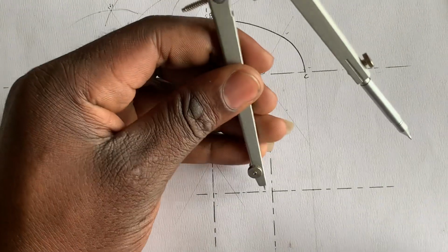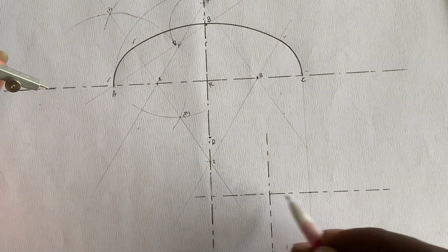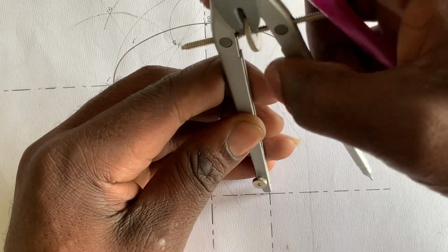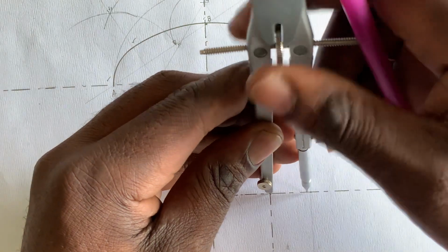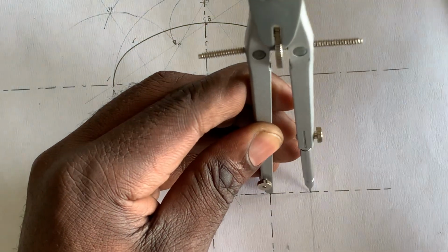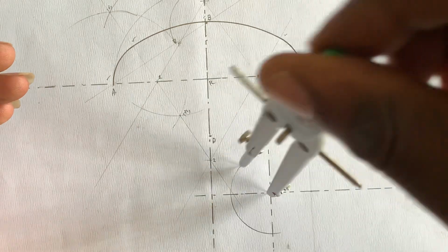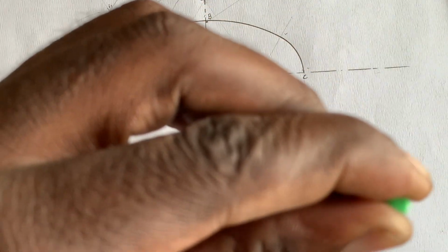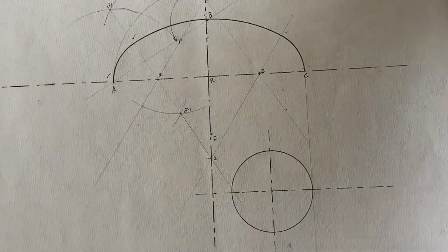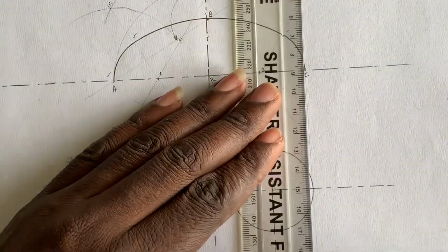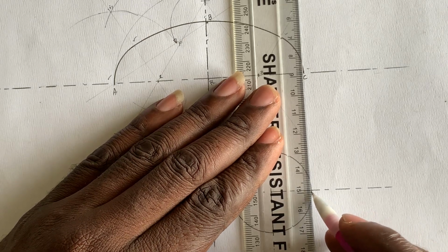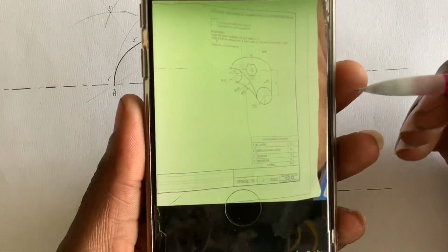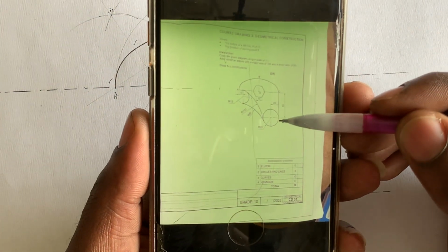So you simply open your drawing compass. Remember that R20 is the same as this dimension 20. So radius 20 millimeter, which means you want to draw diameter 40. There it is. Then you draw it solid. Solid dark. There you go. You get it? So now I can simply have this one dark from here till there. A1. Which is which one? This one, from here till there.